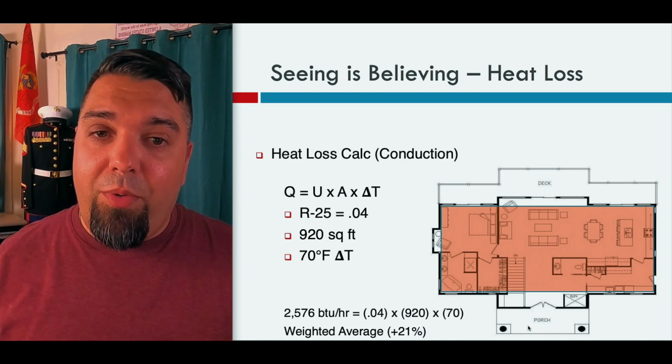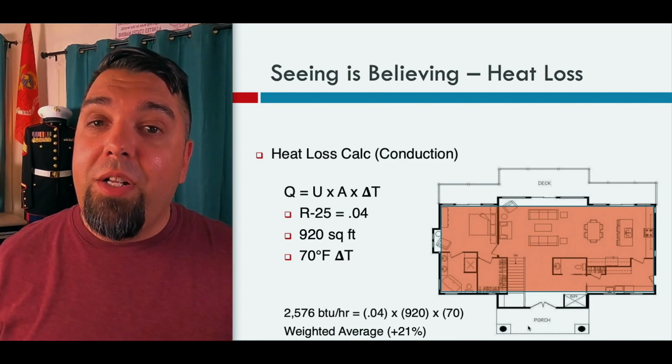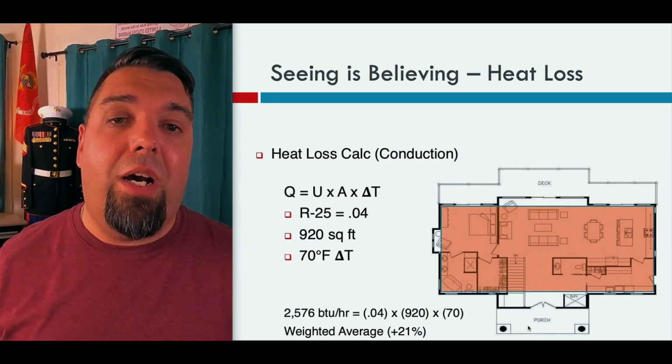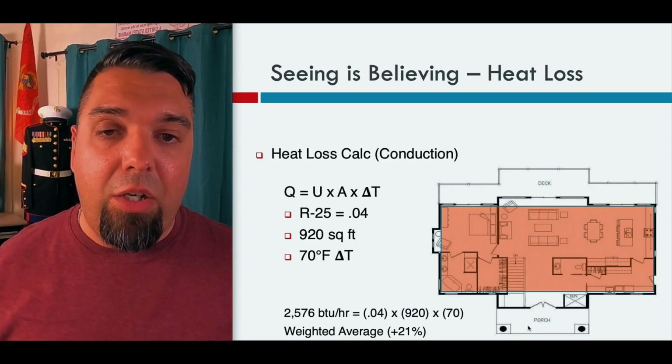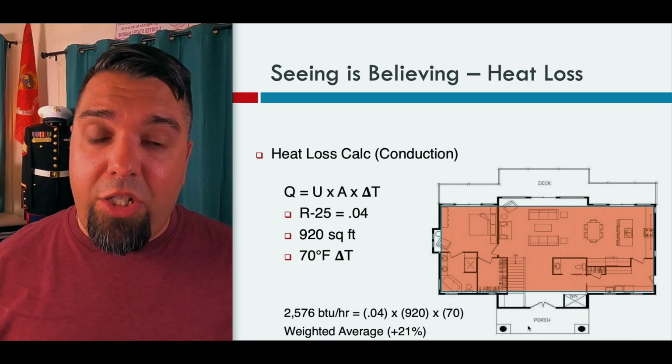So this little bit, particularly in a really low load home, starts to impact the heat loss in every single room when you do duct design or you're sizing ductless or whatever you're doing in order to serve the heating and cooling for those spaces. So really important, use the area weighted sheet, right?